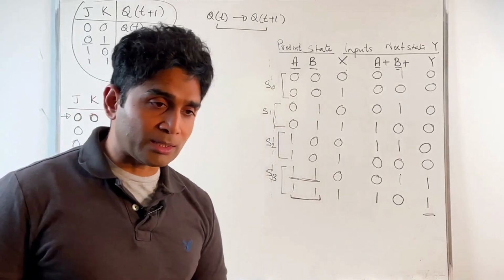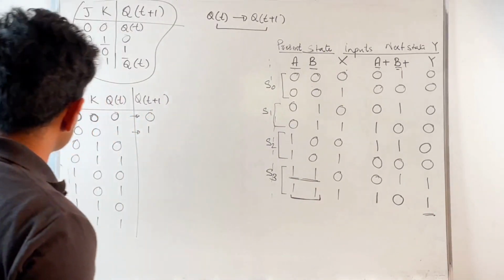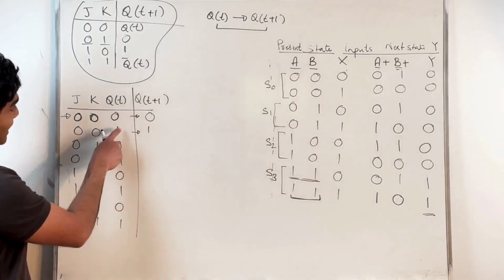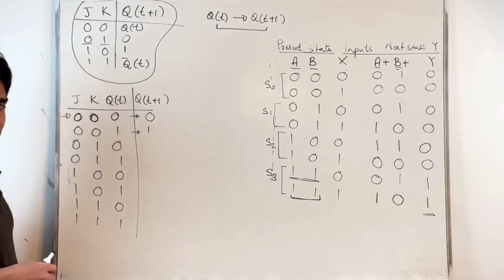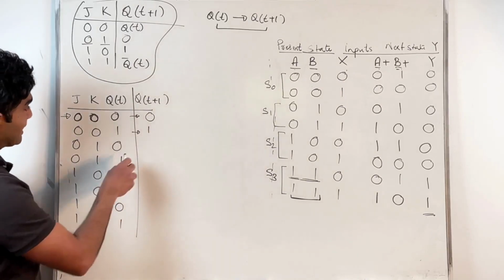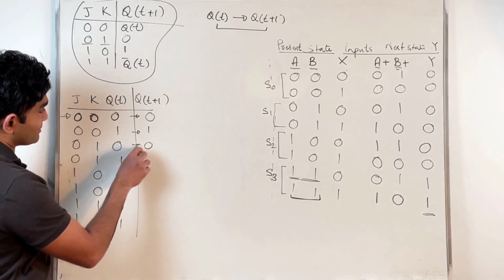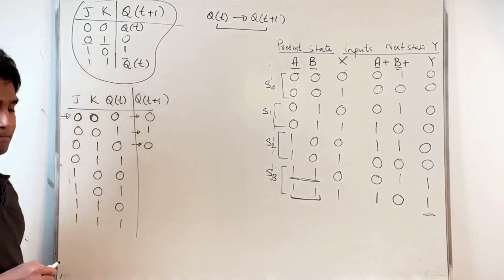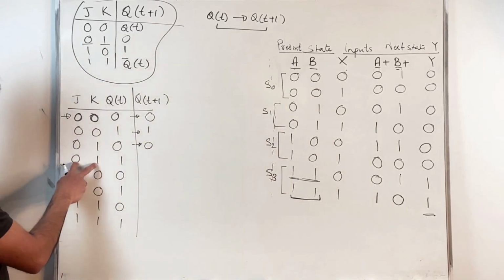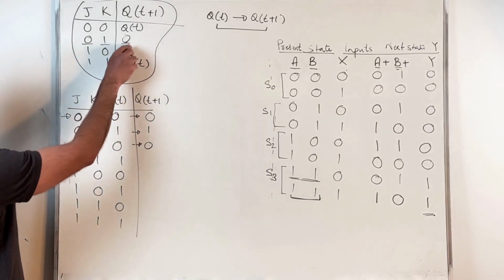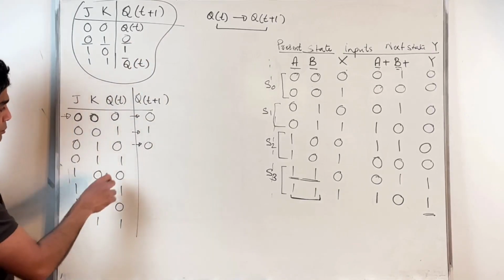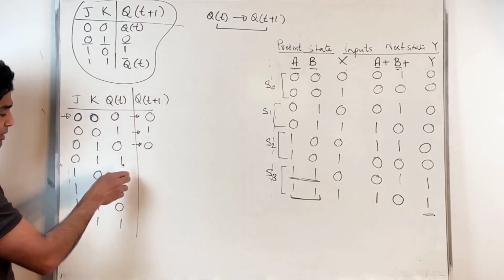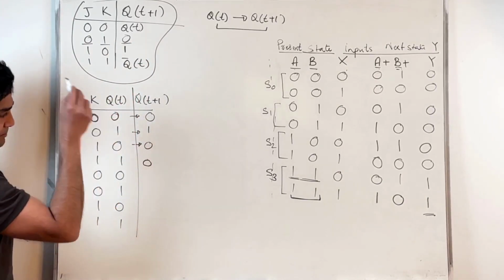Apply a value of 0, 1 on my J and K inputs. Irrespective of what I have in the present output, the output is going to be updated to 0, right? Because that's the reset state. So 0, 1 on J and K will basically reset in the next clock transition. Irrespective of what you have as the present output, that's going to get reset.